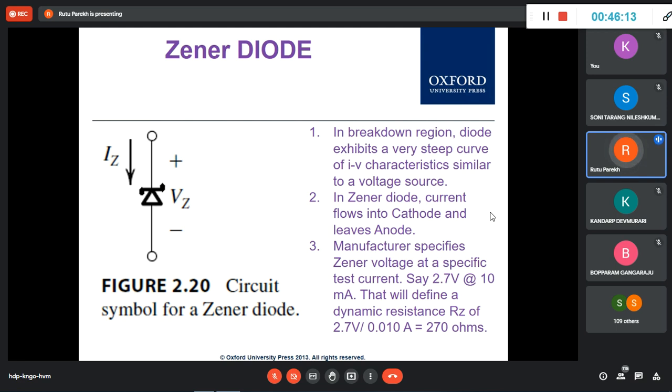So the transformer will still keep AC only, but it will step down your high voltages. And then we convert this step down, as per our need, into the DC. You need 5 volt, some ICs need 10 volt, whatever, 1.8 volt, 3 volt. So then we need accordingly the DC, but your signals can fluctuate. Your AC will fluctuate, then your DC will also fluctuate, and then everything will be destroyed, right?